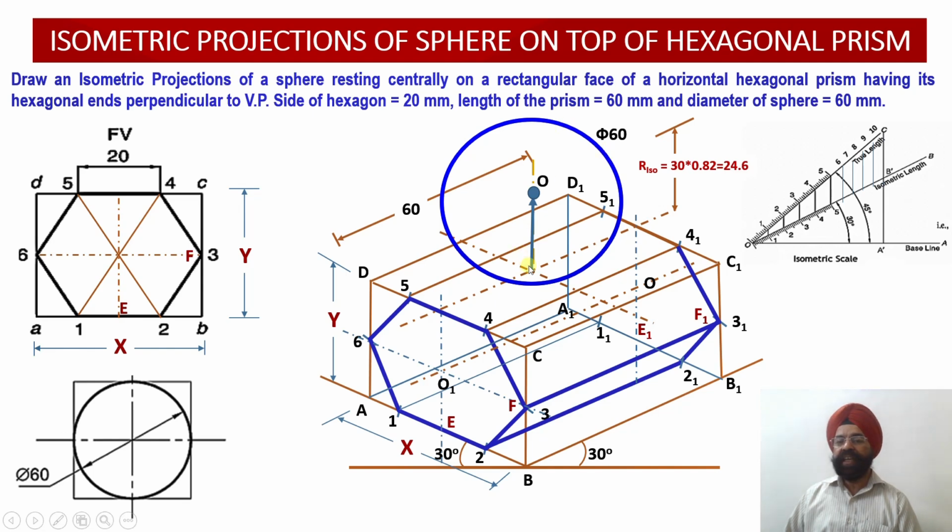So the only thing is the radius has been reduced, but that's the only thing. Through this radius the point O has been located, and then through O, when you start drawing the circle, we have to take the radius equal to 30. Now you can check this around 5.4 millimeter is the distance by which it might appear that this sphere bottom has overshot the center.